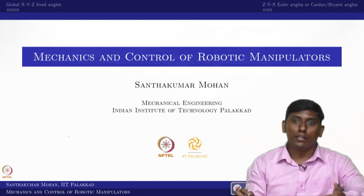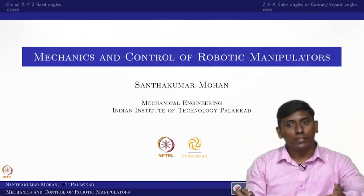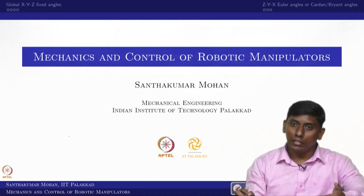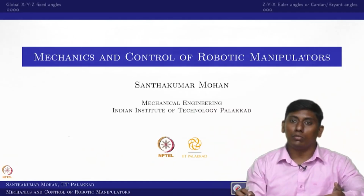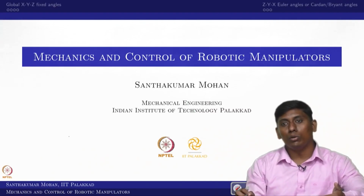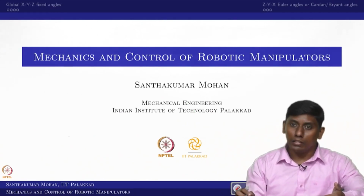Welcome back to Mechanics and Control of Robotic Manipulator. Last class we saw individual rotation matrices, and then gave an introduction to compound rotations. Even in that class I told that we can do two things. If you are rotating any frame with respect to a fixed axis, then you have to pre-multiply that rotation matrix, whereas if you are rotating with respect to a moving axis, then you have to post-multiply.